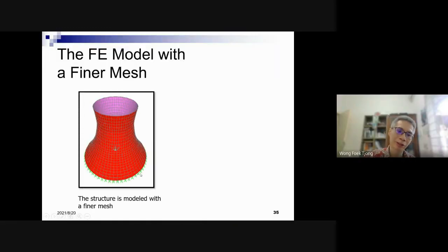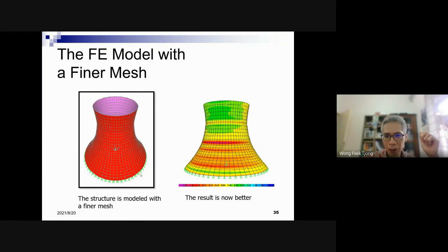This is cells. If we talk about cells, what we expect from our static analysis is that we want to know the membrane forces. The membrane force means the in-plane force. If you attended my workshop, I explained that. There are two types of in-plane force: one is tension or compression, the other is shear.